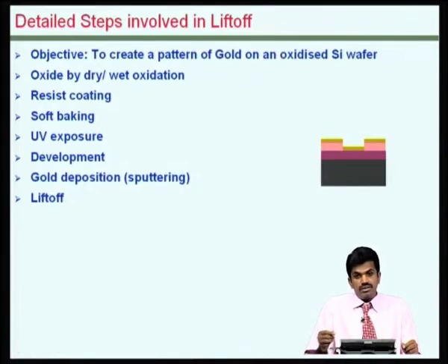But we can't just keep on increasing the thickness of the resist, because if you have it too thick, it may not develop well, it may not expose well when you use a normal UV light. So, we need to have some kind of a compromise between the thickness and the coverage.